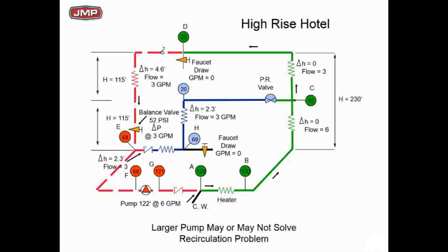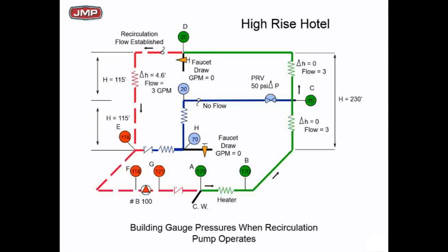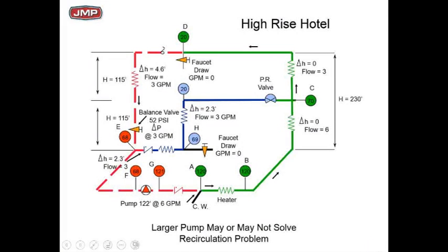I'm going to take 52 pounds. And when I take that 52 pounds of drop, I now have the 68 pounds red, where before it was 118. I'm down to 68 now. So now my blue recirc line will flow into my little red recirc line there if that pressure is that low. So everybody see how we can make it? We balanced it. But what a huge penalty in energy cost, what a huge penalty in a pressure drop to make it work. This is how we made it work.